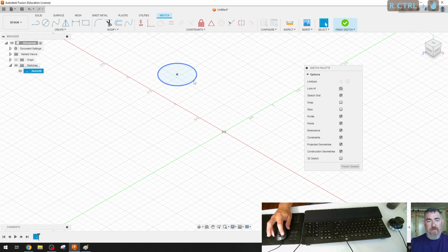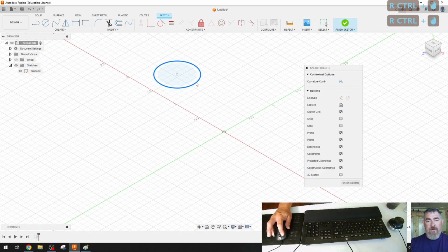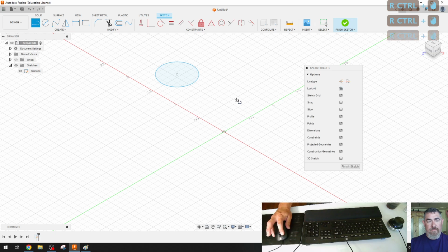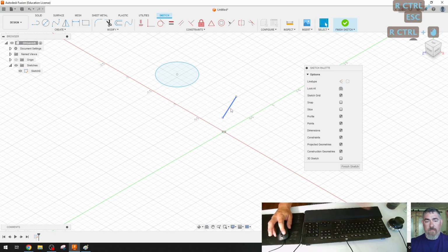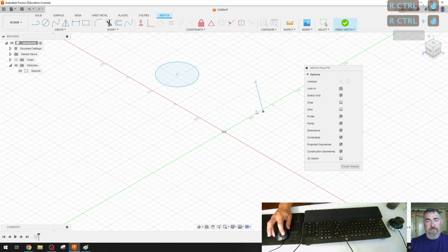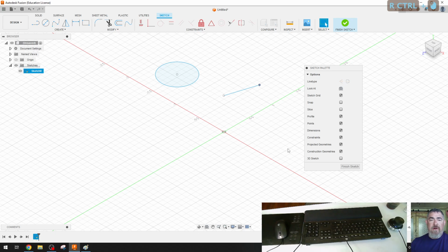I can also go to the outside of the circle, click and drag to make that bigger. If I have a line, I can click on the line and drag the line, or I can click on the endpoint and drag the endpoints. So now I'm pressing and holding the mouse as I'm doing that. Keep that in mind as you're doing the different things in this activity, so you really get a feel of what's going on with the different constraints. All right, thank you.